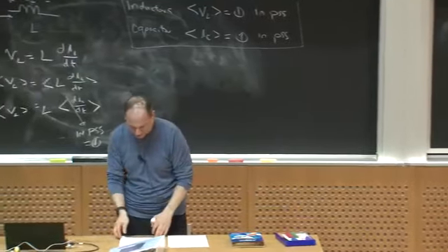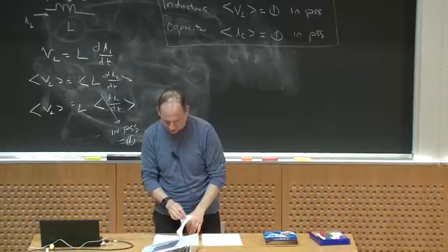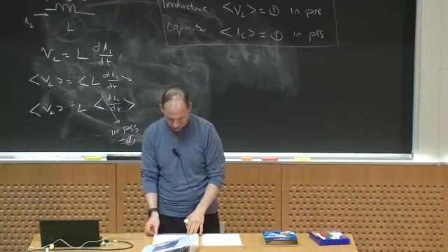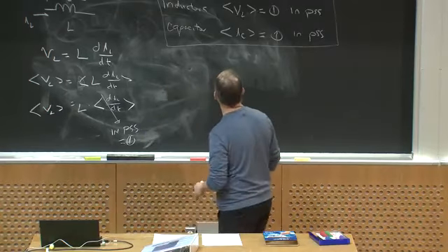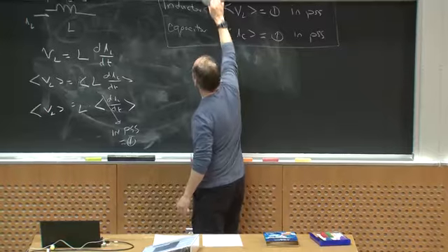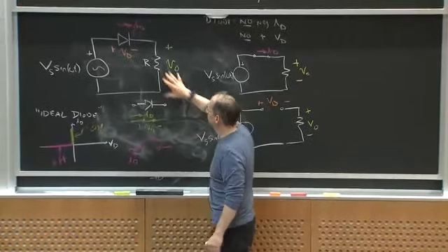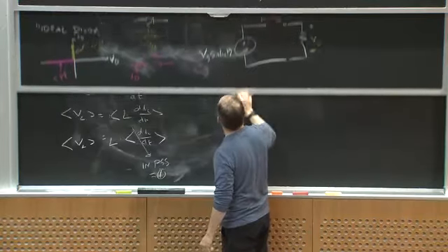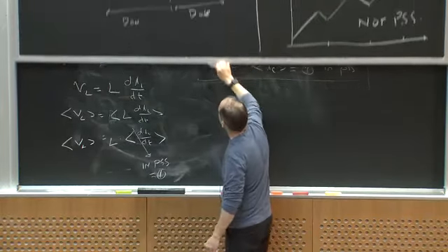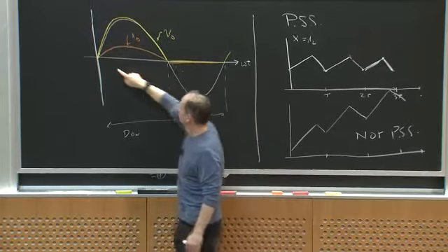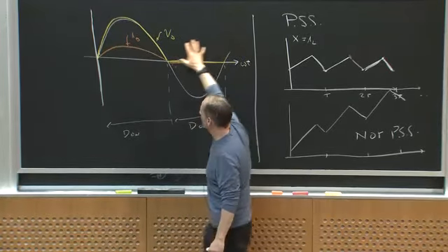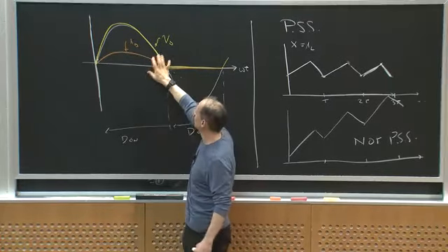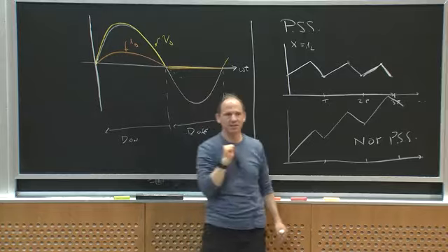So let me just give you a super simple example of that and sort of how it can inform your thinking. And here's the circuit I'm going to do. Suppose we came back to this circuit, okay? And what I got when I looked at that output voltage, this voltage here, is sort of a periodic steady state voltage. It actually has a DC component, so that thing is actually the world's simplest rectifier. It takes an AC voltage and generates an output voltage that has a DC component, right?